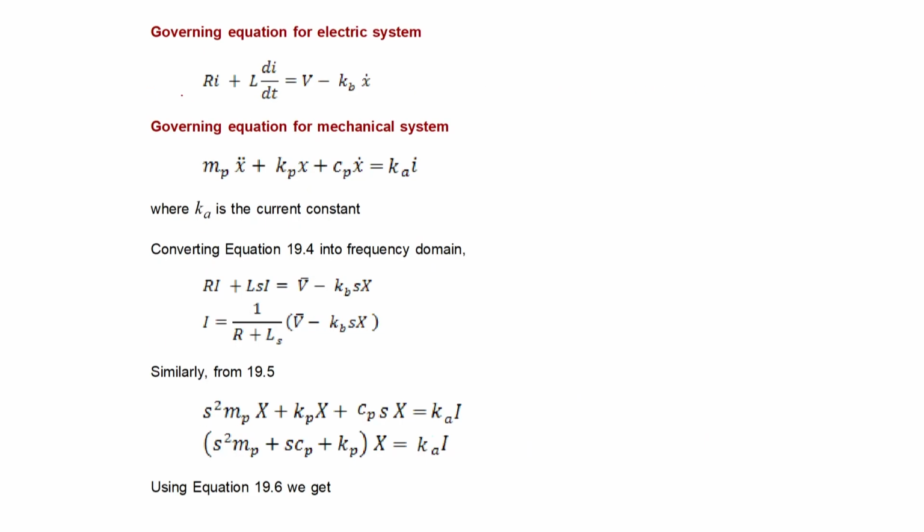This is like a similar electrical circuit, with one important difference: you are getting a back EMF because of the vibration. The velocity of the proof mass actuator generates a back EMF, which works against the voltage, and the governing mechanical equation of the system has this actuation force involved with it.